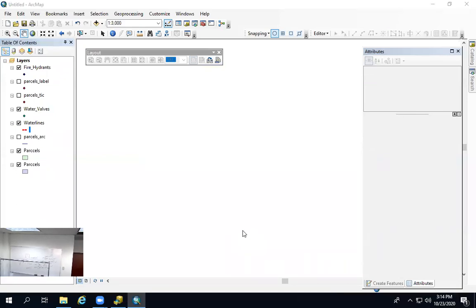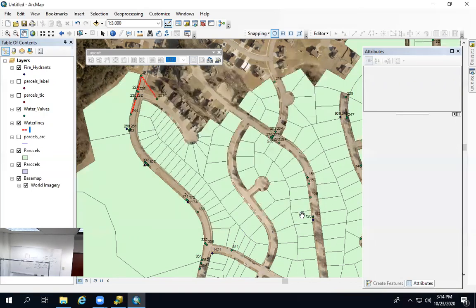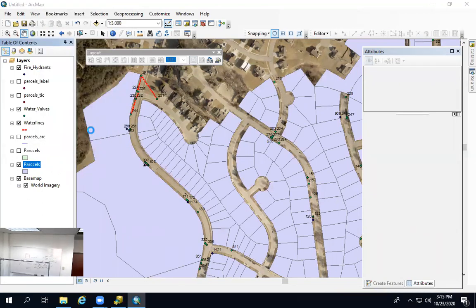You notice here, I can see some of your computers are faster than mine. Now these purple or pink layers, you can see there are new parcels there. Let's build a new parcel. But first, it looks very ugly. I want to see the actual aerial photo. So let's create some transparency for this layer. I'm going to go to this green parcel layer. I want to create some transparency to it. Right click, properties. I'll make it a little bit transparent so I can see below it.